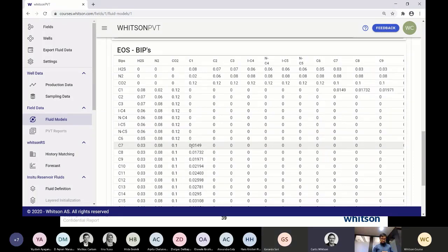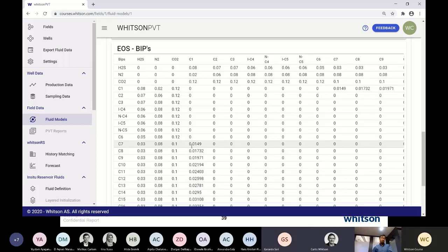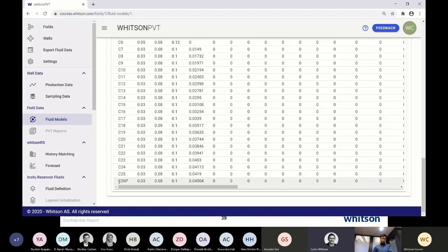Now, having said that, what you could say is that you have to be very careful with having larger binary interaction parameters for the heaviest component with methane, because of the PVT data you're fitting. You don't know what large means, but contrasting BIPs, like, what's the heaviest component here? C26. Let's say we have these BIPs here: 0.0419 for C1 to C5, which is about what Katz and Firoozabadi recommended back in '78.